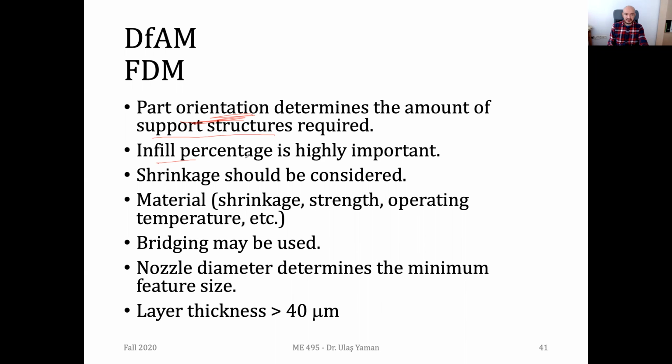Another thing is the infill percentage. If the strength is not important for you, it's always better you have less infill percentages. This will decrease the overall weight and decrease the material consumption. Another issue is the shrinkage. Usually we have 1 to 3% of shrinkage in fused deposition modeling. You should be aware of this issue, especially for fitting problems. If you have an assembly and if you don't consider the shrinkage, then probably the resulting part will not fit into your hole exactly. That should be considered while designing your parts.